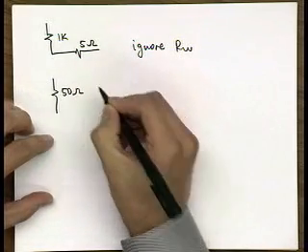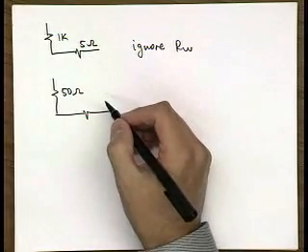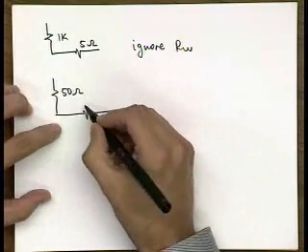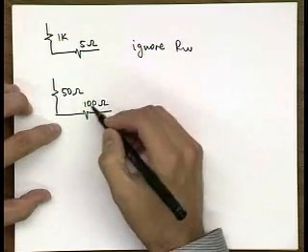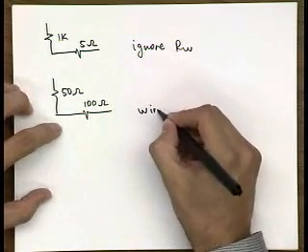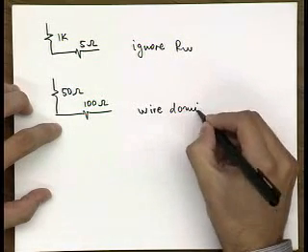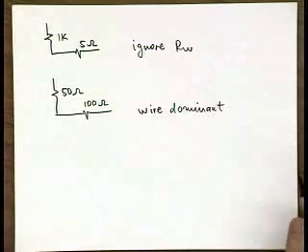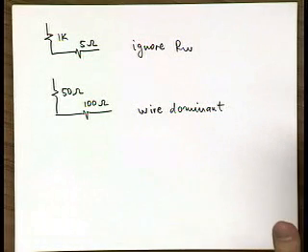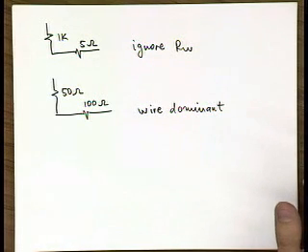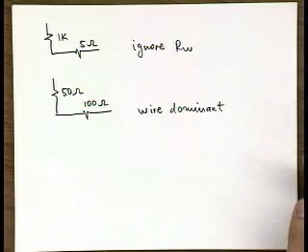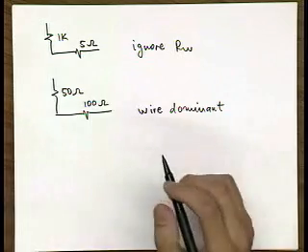Now, another case: when you make your transistor really large and your driver quite strong, for example 50 ohms, and then you have to drive a long wire with, say, 100 ohm resistance, then your wire is dominant here and you need to include it. The question is really, when do I consider the impact of the wire, and when do I not? What you need to do is compare the propagation delay of a gate and the propagation delay of a wire. When you understand the two, you can derive some rules for when you need to consider the wire and when you don't.